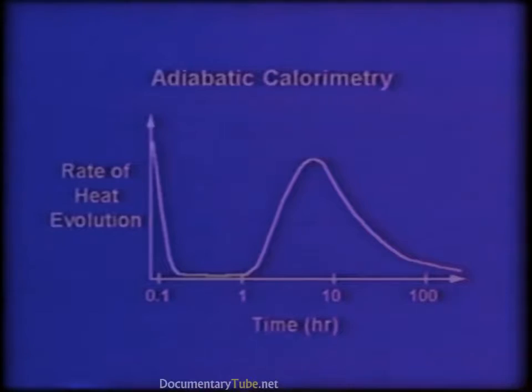The initial dissolution of cement produces a short release of heat, shown by the first peak in the calorimetry curve. After the initial dissolution, hydration products are quickly precipitated on the surface of each cement particle. The layer acts as a protective barrier and temporarily delays the further dissolution of the particle.